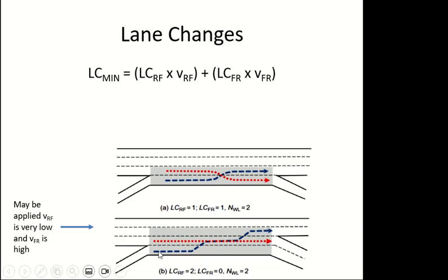Okay, just an explanation of why we will have 2 lanes here. This could be because the flow coming from the ramp is very low, but the flow going from the freeway to the other ramp is very high. So that's why.